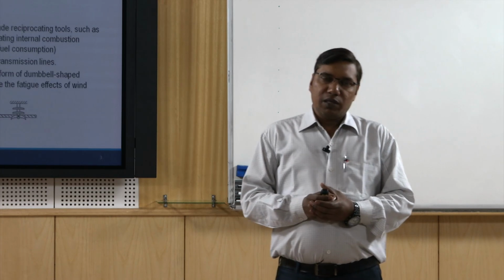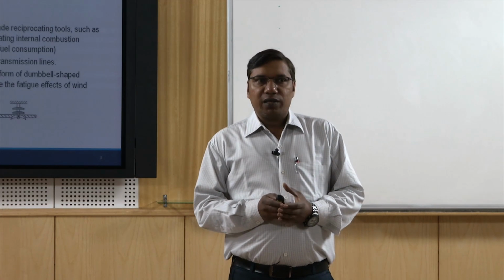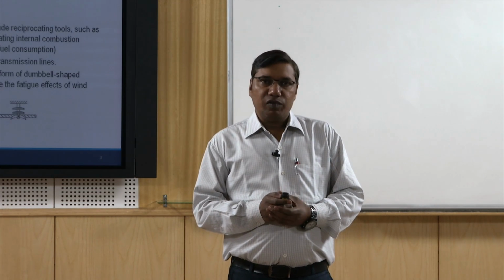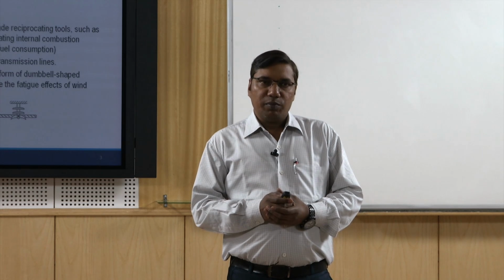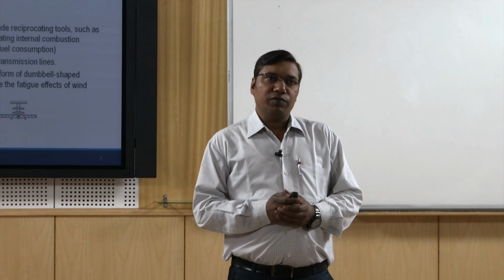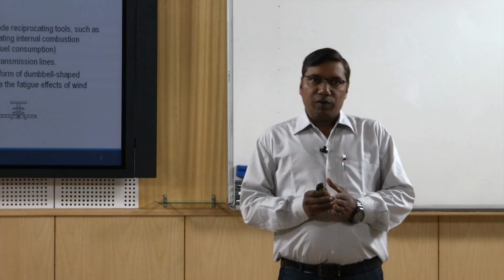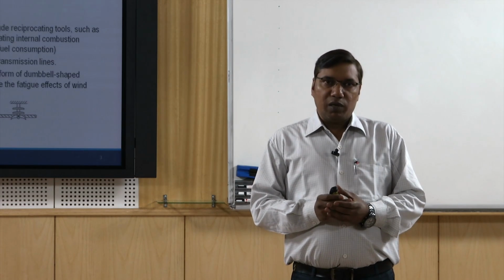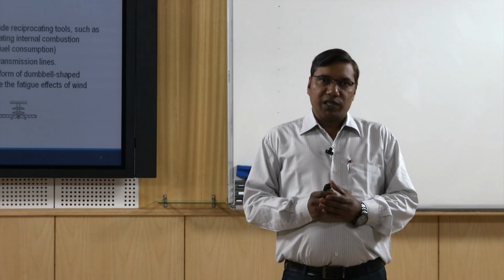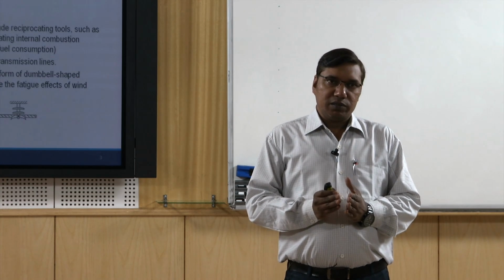These systems can work in a very narrow band of frequency range because they are tuned for a certain frequency range, and therefore we also call them tuned vibration absorbers.